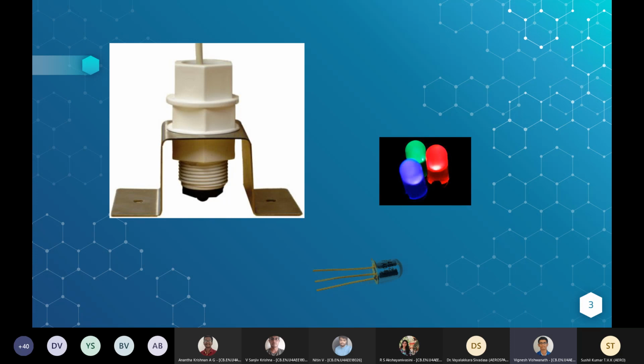When there is no brake fluid present, there will be a particular intensity of light that the transistor will detect. Now let's say there is brake fluid inside the setup. Since there is a fluid, which is the oil here, there is a change in the refractive index compared to the previous example. So the intensity of light that the detector detects will be less than in the empty reservoir. In the actual case, when the reservoir is full of fluid, it has a particular refractive index which will lead to a particular intensity.